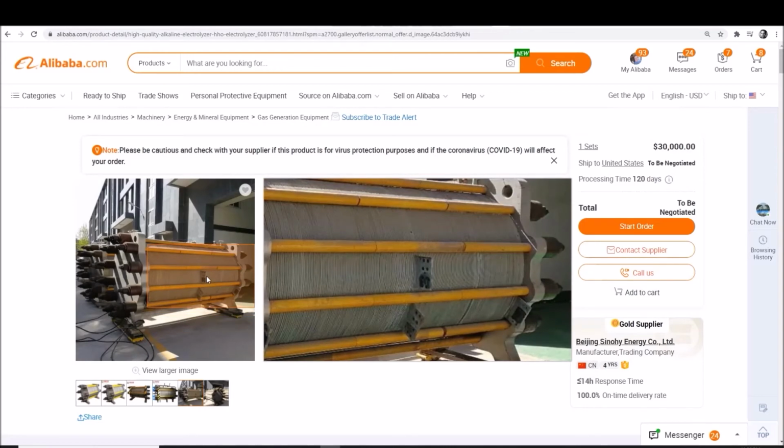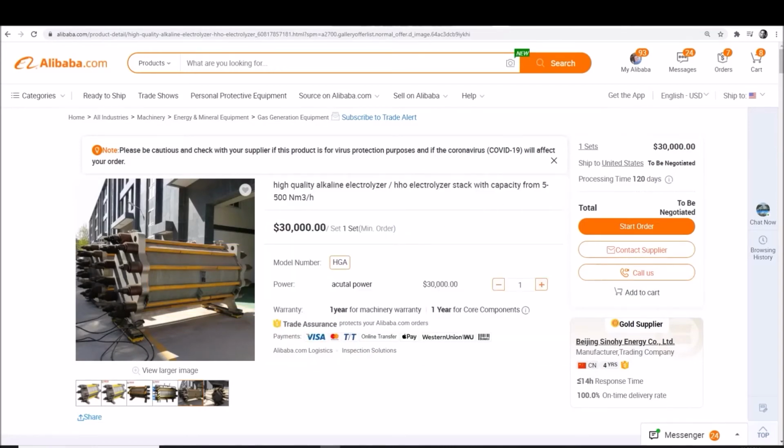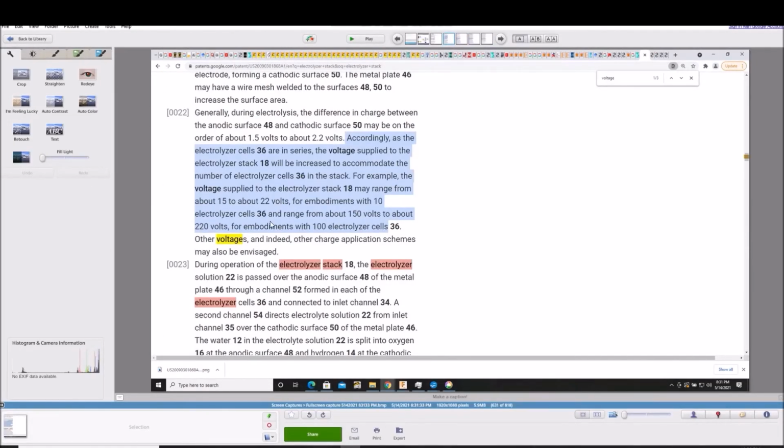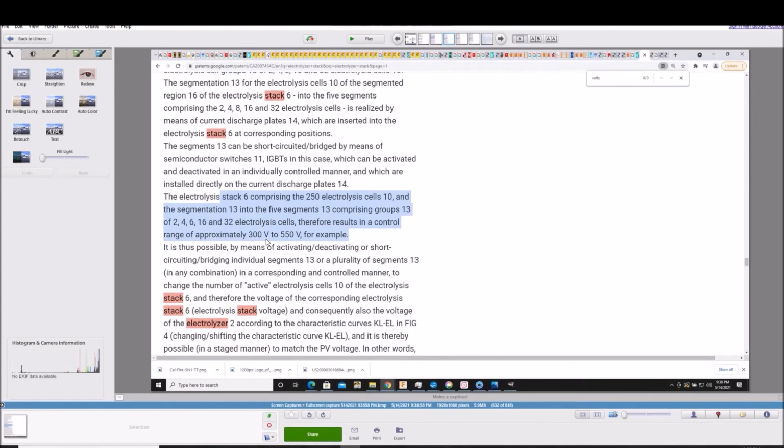Now, essentially the reason you have to do this is because you can't provide 2 volts, right? There's no power supply in existence that can do that, because most electrolyzers, even if they're running off a solar farm, convert from AC first, feed into the AC mains and then rectify back to DC, typically, again depending on the size of the electrolyzer, anywhere from 50 volts to 250 volts.